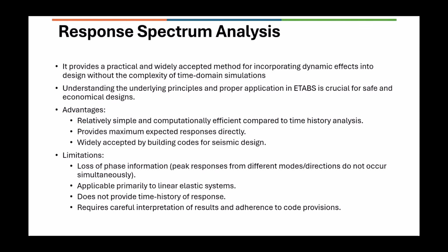That's what we are interested in, and it is widely accepted by building codes around the world for seismic design. The limitations are that we lose the phase information, that is, the signs are lost. That means the directions in which the response is occurring are not available at the end of the day. That is something you should keep in mind.